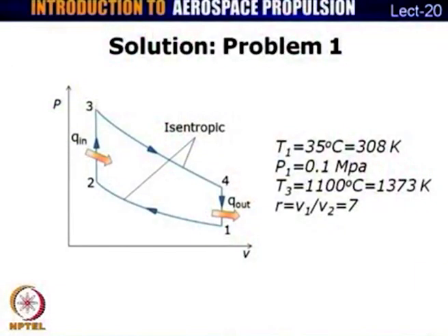So, let us take a look at the cycle diagram for this process. I have in this problem used a PV diagram. In some of the later problems I would be using a TS diagram as well, but it is entirely up to you to draw either PV or TS or both these diagrams. In the PV diagram, an Otto cycle process looks something like this. The process begins with an isentropic compression, that is process 1-2, isentropic compression, and after the process reaches state 2, there is heat addition at constant volume.